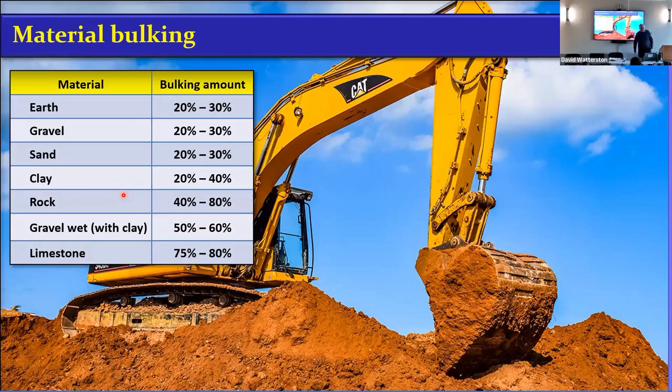I need a second truck. So you don't want to say, well, I did tell you that. And then he says, yeah, but it's all down to bulking. I priced you for one truck, not knowing. So you want to make it clear that A, you understand bulking. And you say, I've got 10 cubic meters of soil or clay that I need to get out, gravel, whatever it is. Remember, this is going to bulk up. So you need to give me a price for taking that away and not coming wanting more money for more trucks.